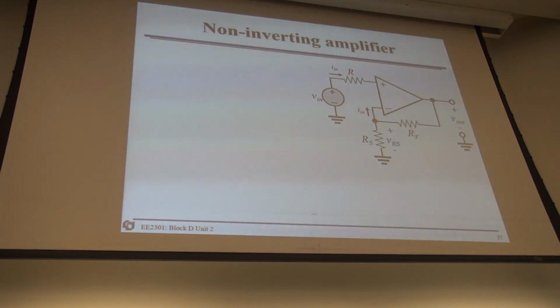Because we don't have current flow into it. Because the open loop amplification of this one is 10 to the power of 10. Okay? We don't have current flow into it. So in other words, the voltage in here and the voltage in here are the same, right? Yes? Yes. And also our I in here should be 0. Okay, this is a very important concept. We don't have anything flowing inside. It's so small. Okay, ignore it.